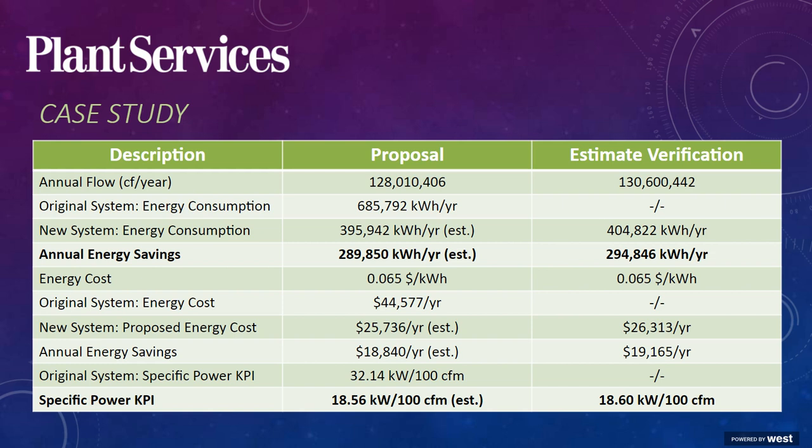So this case study, while several years old, is certainly relevant today. In this case, simply adding a VFD compressor without augmenting the piping would have most likely resulted in the same problems occurring. And we probably wouldn't have known what those problems were if we didn't do an air audit to start with.